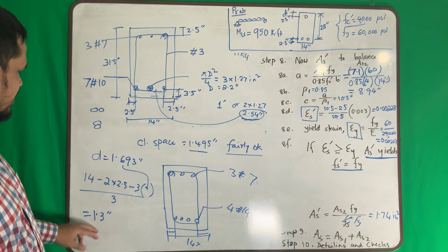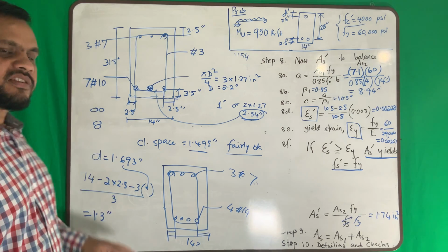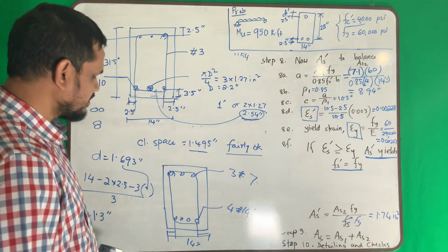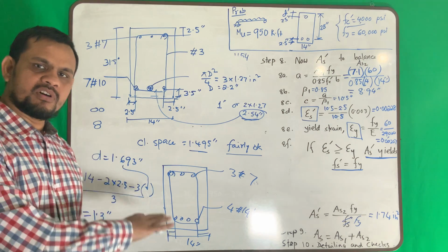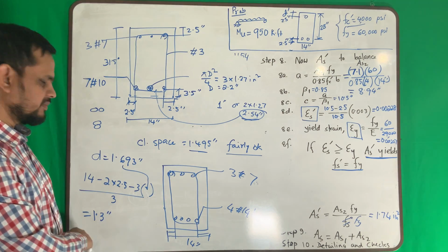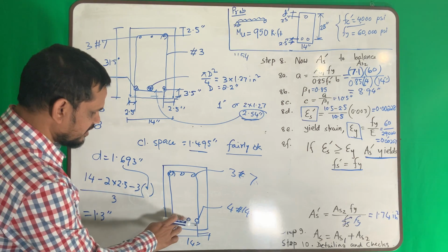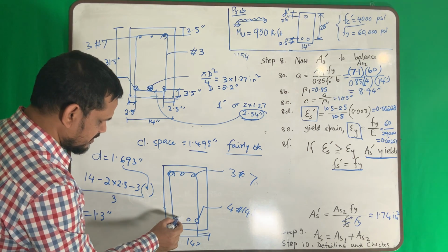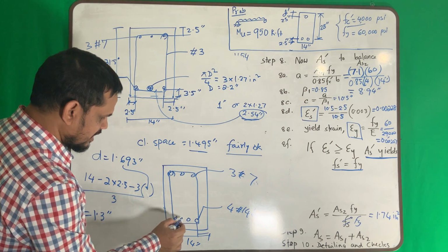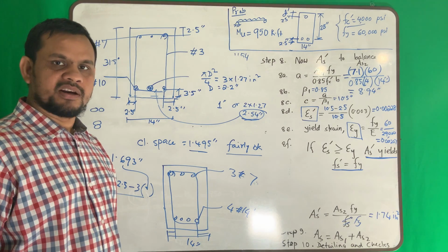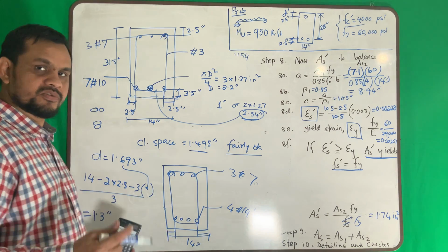How much do I need? At least the bar diameter. Is still not good. But again, this is also an option, although it is mathematically not correct, but you can. Or, yeah, number 14 bar, I think you cannot bundle it because it is so big.